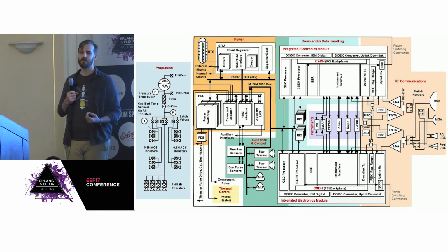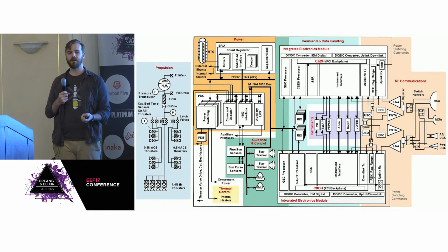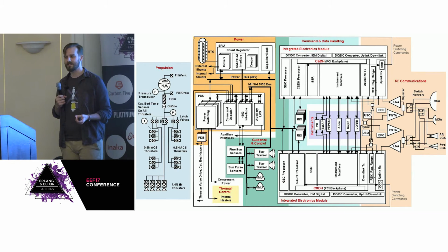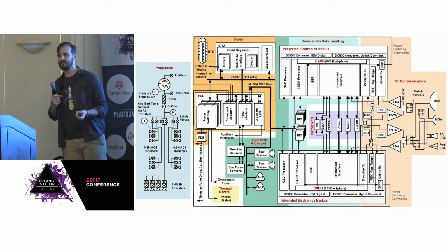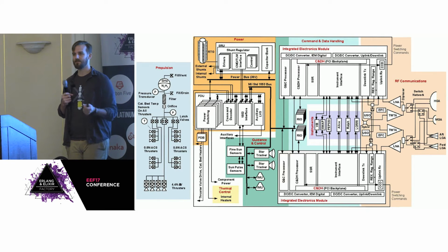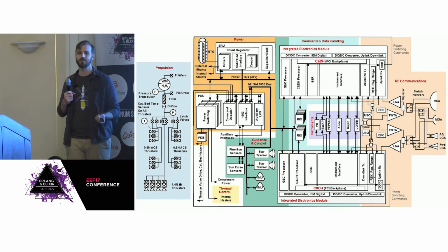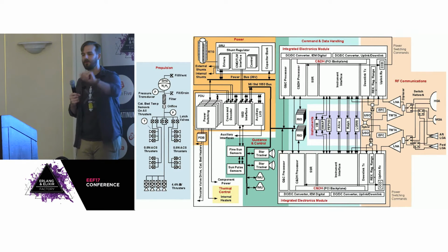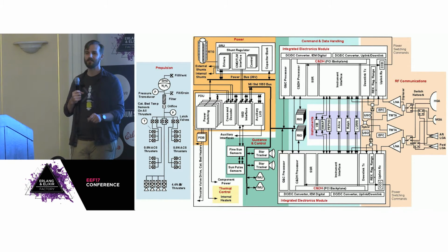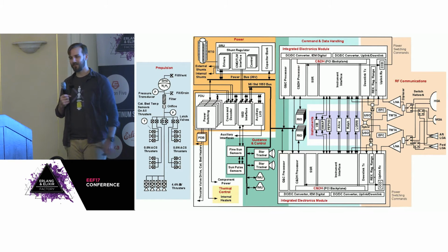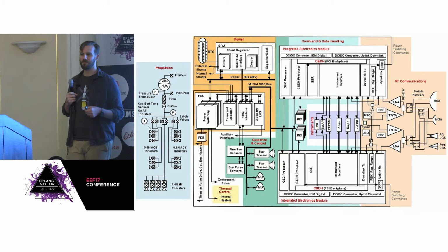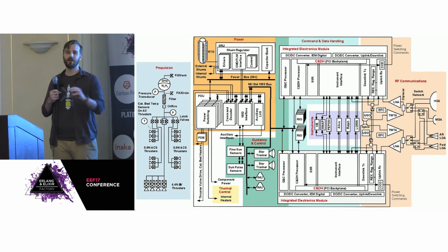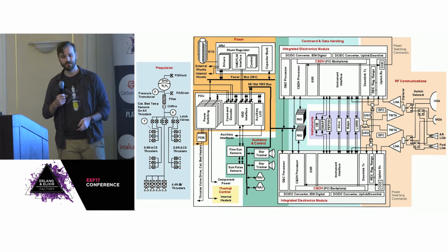And safe mode for New Horizons is pretty fun. Safe mode for any spacecraft is pretty fun. It can't come back for repair, so they have to point themselves at a well-known spot so that we can interact with it. So safe mode for New Horizons is either Earth safe or Sun safe. Sun safe is the least preferable, as I understand it, because there are fewer opportunities for pointing the deep space network at it. Earth safe is the best. But that means that even in a degraded state, New Horizons still has to be able to do orbital computations to figure out where in the solar system the Earth is, because it has to keep pointing at the Earth. You have to understand that New Horizons is flung out of the solar system. It's achieved solar escape velocity. So it's important for it to be able to, even when it's deviated by gravitational perturbations, point at a well-known place.